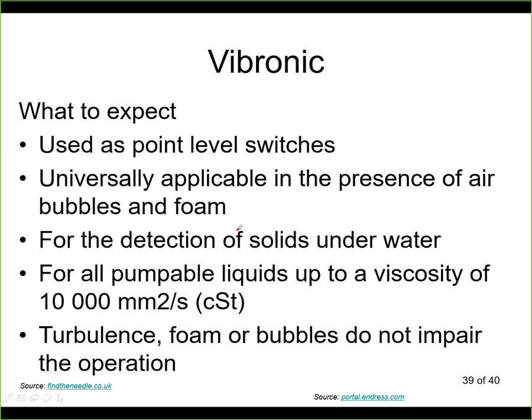At the end, let us see what we can expect. Now this is only a point level switch, so no continuous reading. It can be used when you have bubbles and foam. That's not a problem, because you are looking for the liquid level. It can be used also to detect solids that are underwater.